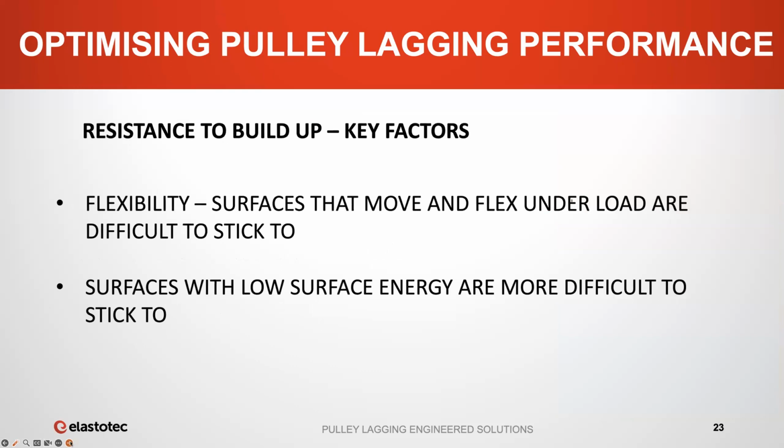When we look at the second important criteria for lagging on non-drive pulleys, resistance to build-up, there are two physical properties that have a direct impact on this: flexibility and low surface energy. Flexibility allows the material to resist sticking by moving and flexing under load. It effectively prevents the material from attaching to a fixed static surface. Low surface energy is indicative of materials that are difficult to stick to.